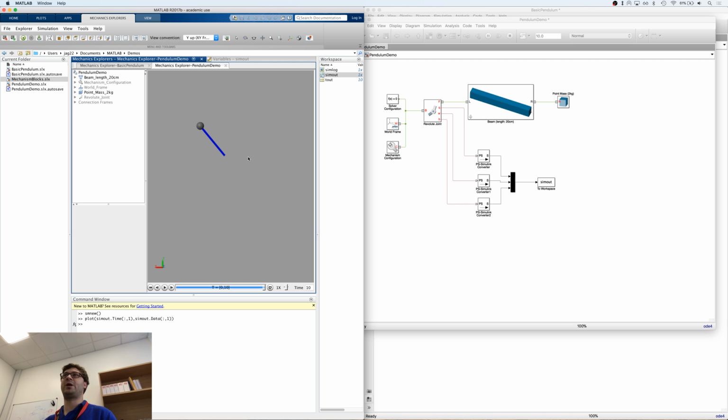In your mechanism design, when you're generating your mechanism for the car convertible roof, you'll be powering your mechanism through a motor. The motor will have to use a feedback loop based on the speed at which that mechanism is running, because you'll be working up and down a motor profile. So this is a really quick short demo showing you how to take a sensor reading from your joint, use that to calculate a new force or torque on your system, and feed that back into the joint.